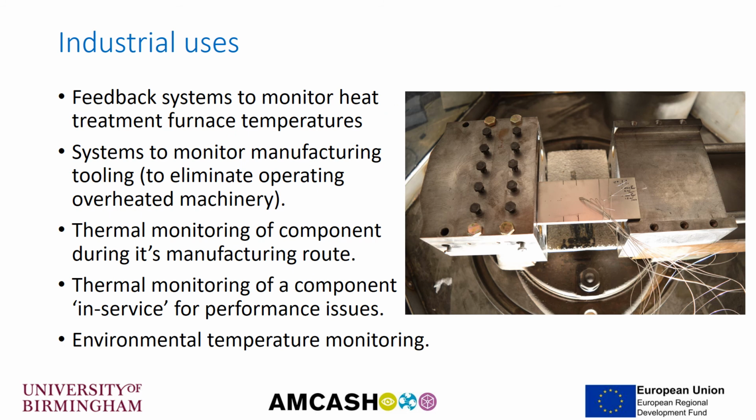And so if we think about what industrial uses we could have for thermocouple measurements, then perhaps a feedback system to monitor the temperature within a heat treatment furnace. We could look at having systems to monitor manufacturing tooling temperature during a manufacturing route. We could monitor the components during a manufacturing route. We could monitor the temperature of a component as it's in service and see if there are any performance issues there. Or we could look at standard environmental temperatures over a given time frame.